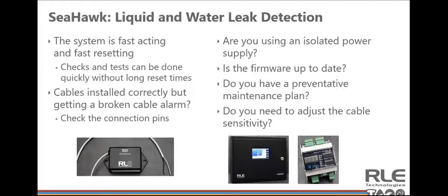Another thing I have found is to really inspect the area that you're trying to detect leaks in. I have seen in my days everything from 10-gallon water heaters, water drainage piping from a roof, all sorts of other unexpected piping in drop ceilings and attic spaces, and those I have seen cause problems. Specifically, a condensation management system in a data center that overflowed and started raining onto a SAN unit. Talk about a bad day for that data center manager.